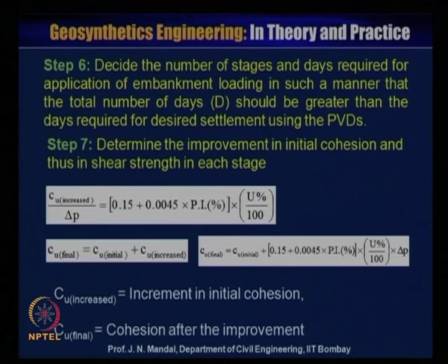Step 6, decide the number of stages and days required for application of embankment loading in such a manner that the total number of days should be greater than the days required for the settlement using the prefabricated vertical drain. Step 7, determine the improvement in initial cohesion and thus shear strength in each stage.